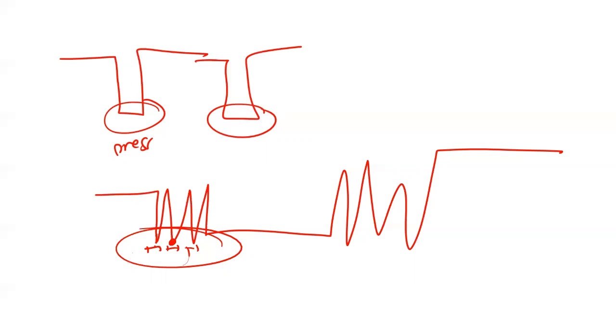Is that okay? For sure, this time from here to here is a very little time, 10 milliseconds or 15 milliseconds. Very little time. There is no human being who can make 3-4 presses in 10 milliseconds. You got what I'm saying? So this is the problem. What's the problem again? This bouncing period is about 10 to 15 milliseconds. There is no human being that can make presses that fast, right? 3-4 presses every 10 milliseconds. We cannot do that, right?